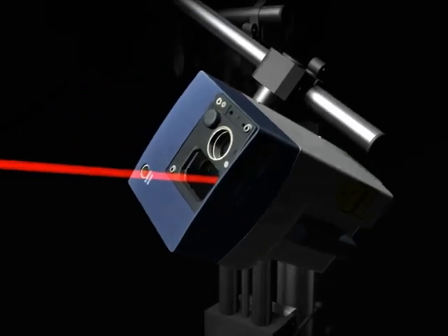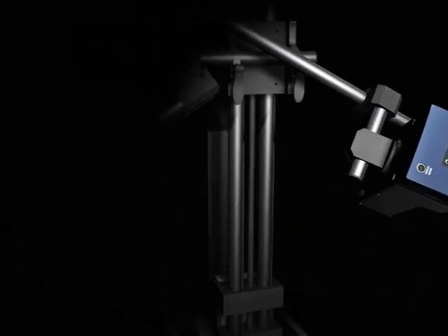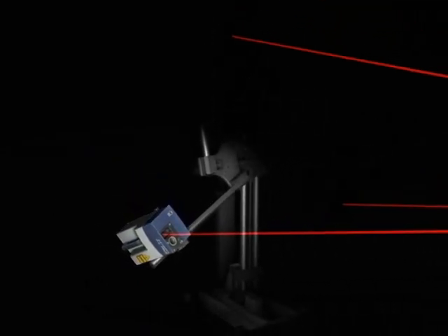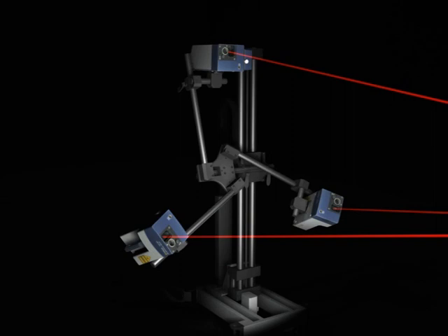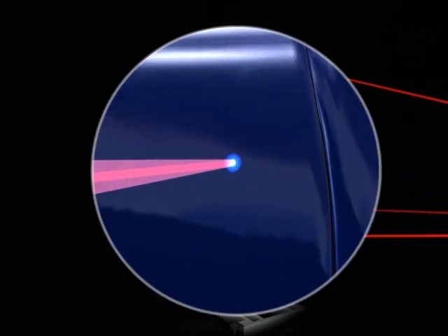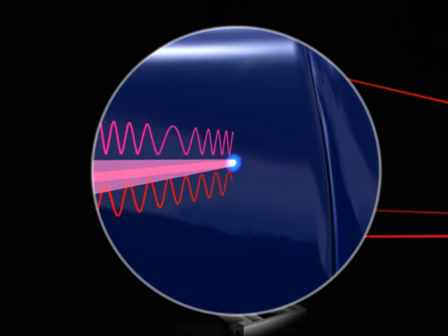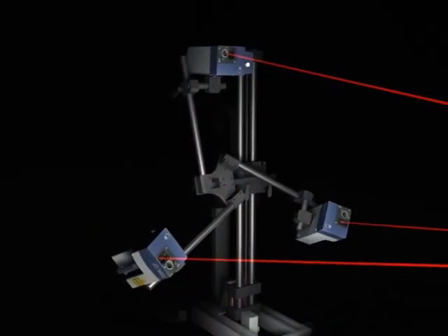Discover the advantages of 3D scanning laser vibrometry and learn how vibration measurement is done quickly and effectively with superior technology from Polytec. Laser vibrometry uses the Doppler effect for non-contact optical vibration measurement. The effect describes how the frequency of light is changed slightly when the light is scattered from a moving object.